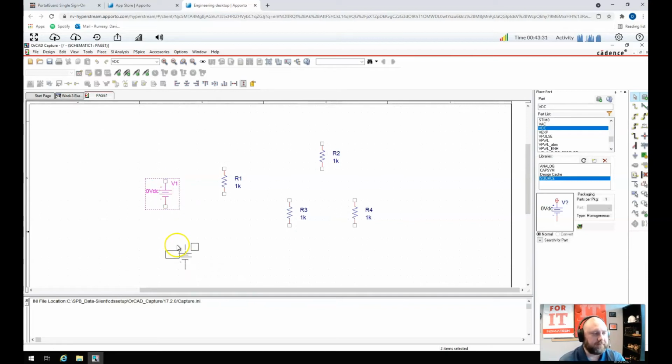That's my battery. Now, one thing the diagram doesn't have, which I think is, in my personal opinion, a bad diagram, is it doesn't have the most important component on there, which is ground. You cannot simulate without ground. It doesn't matter how everything's connected, you need a ground. And a way to get a ground is to go over here with this place ground. And again, I could hit the G key for a shortcut, which is what I'm going to do.